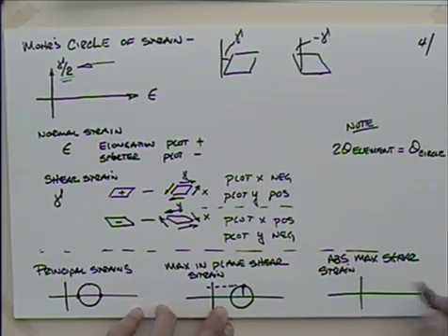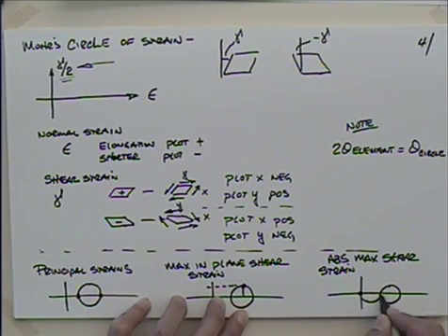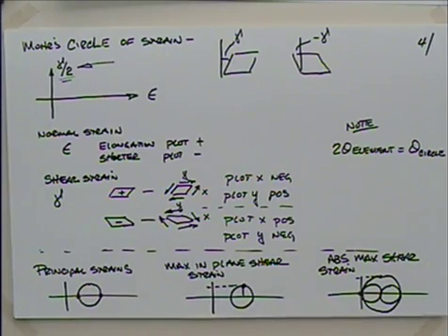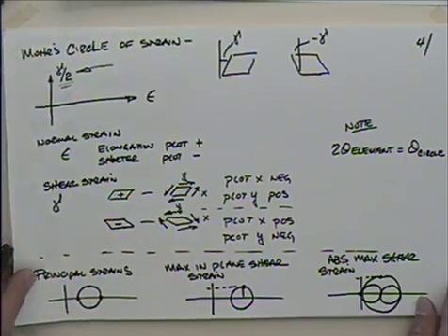If we have a given situation like this, maybe we're given a circle like this, and we recognize that in the z direction we have 0, we actually have another circle, don't we? And now we need to find the radius of the largest circle. So the same things that we talked about, maximum in-plane shear stress and absolute maximum shear stress, work for strain also. The terminology can be easily converted. Well, with that, let's get started with a problem just to try and pull this all together and hopefully show that it's not as confusing as it might appear.